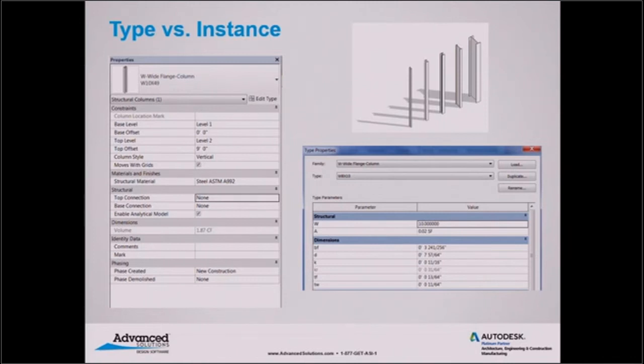It could be the same shape wide flange, but they could have different heights, okay? But the things that are unique to each W8 by 10 are the things that make it a W8 by 10: the flange thickness and the flange width and the web thickness and all those kinds of things that define that shape are common for every W8 by 10, okay?